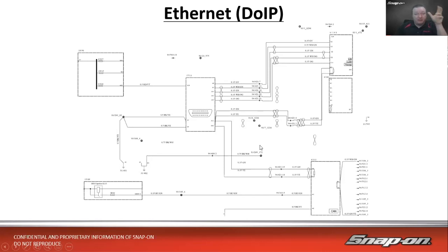All Ethernet on this car is internal, inside. So when we communicate with it, we have to go through the gateway module. The gateway then translates it to Ethernet for the rest of the engine, the transmission, the higher speed information that we need inside the vehicle. And I've found that's the case in many vehicles, not all vehicles, but many vehicles. It's CAN or some other sort of more common protocol until it gets into the vehicle, and then it's Ethernet internally.